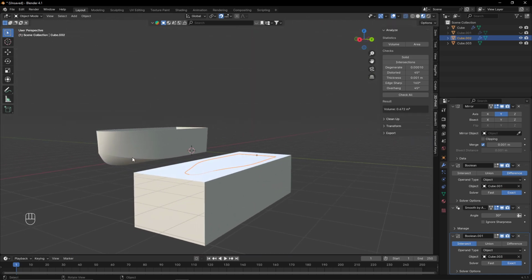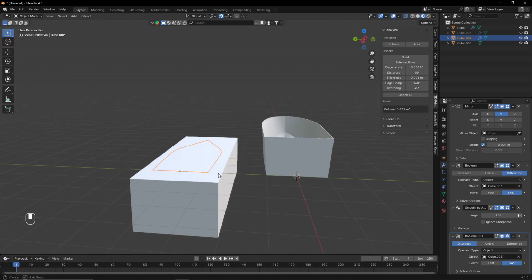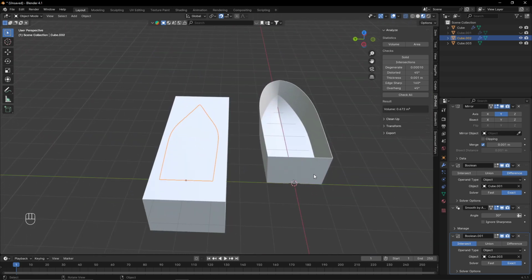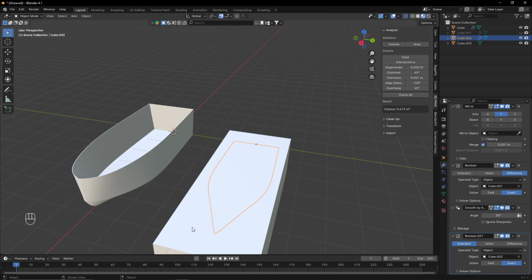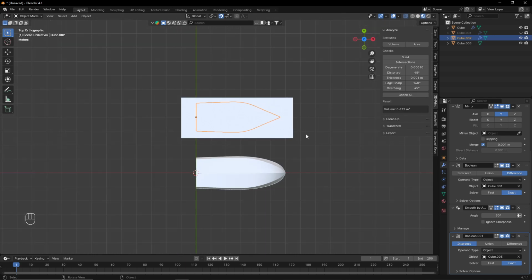So there you go. You might want more, you might want less. Modify the boat however you want, depending on your needs and desires. That's the basic idea. And remember also to look at the surface at the waterline. The larger it is, the more stable the form stability is, the more profiled it is, the better the displacement speed will be, the displacement efficiency.